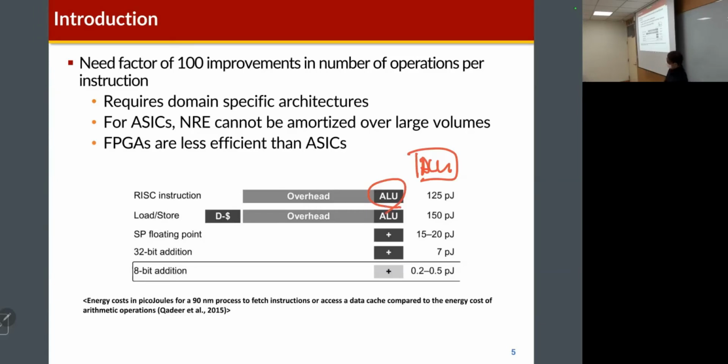But in order to execute a single instruction, a processor requires this amount of power. Why? We learned about out-of-order processor architecture. In order to execute an instruction, it needs to be fetched from the instruction memory, included in the instruction fetch queue, and then decoded and dispatched to the issue queues.